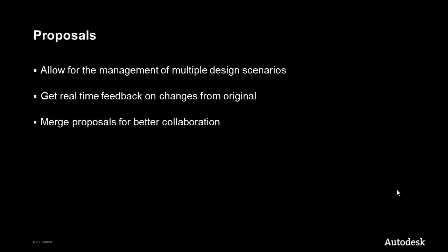The next thing I want to go over are what's called proposals. They basically allow you to manage multiple designs at a time. You can get real-time feedback on the things that you've created or removed from the original, and you can also merge proposals together. So let me show you that.